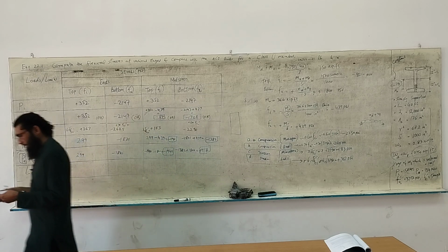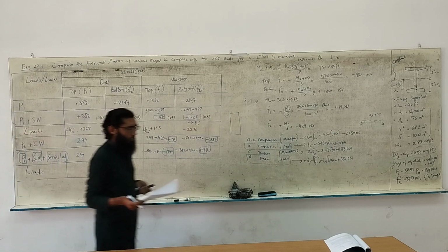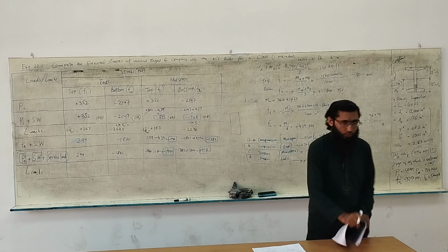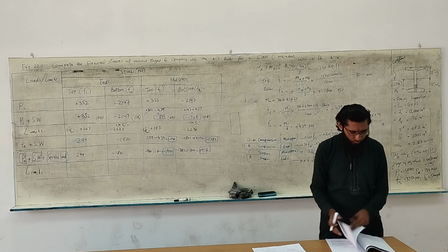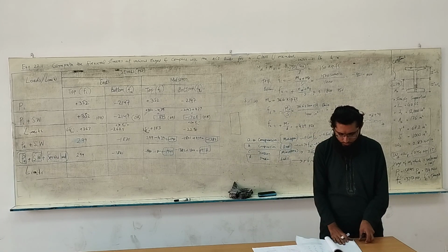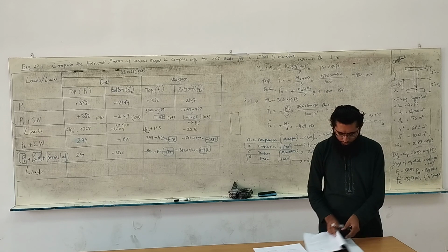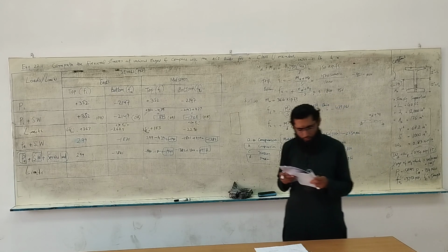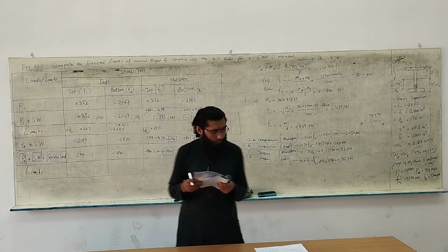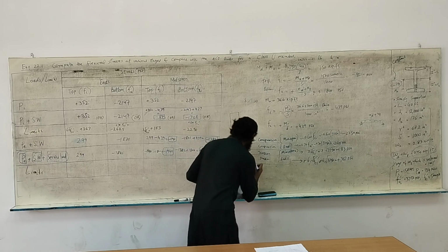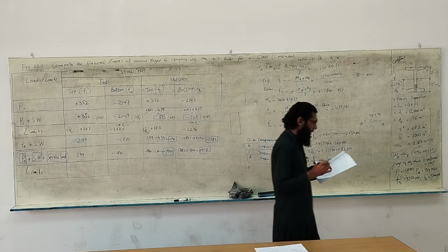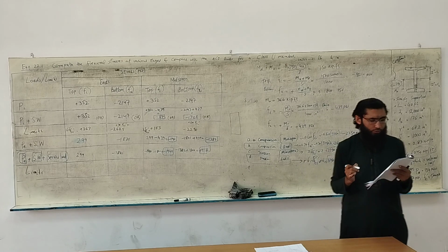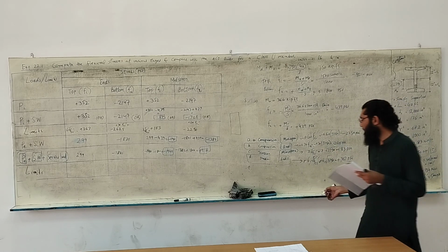Now the limits for these cases are, again, go back quickly to the table. We have done the first 4 conditions. Just quickly go to the table and see the limits for this case. We have limit E, which says extreme fiber stress in compression due to pre-stress plus sustained load.